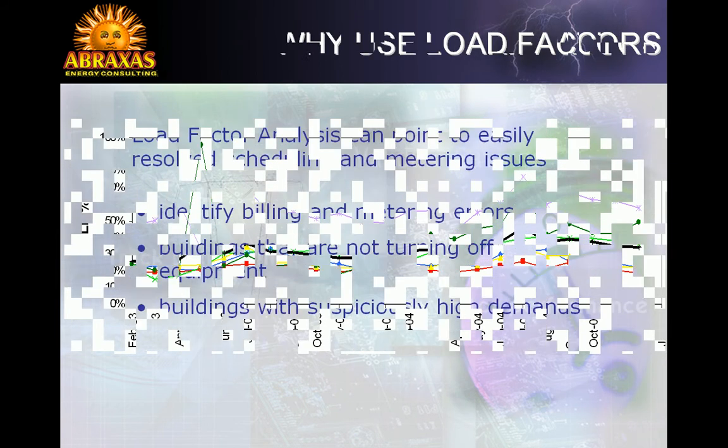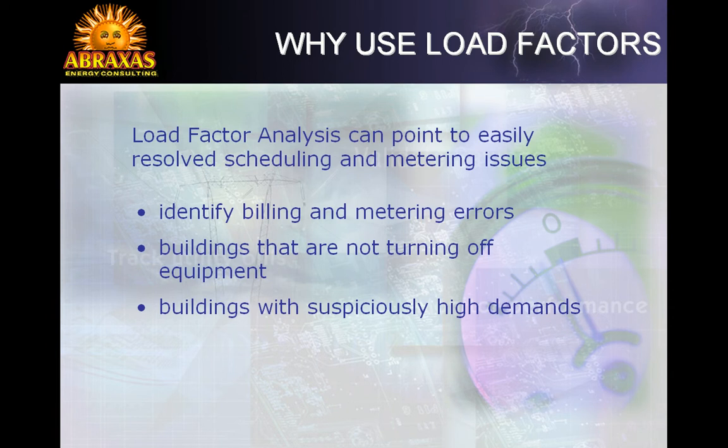Load factor analysis is an art, not a science. Different building types, for example schools, offices, and hospitals, will have different typical load factor ranges. Since hospitals run many areas 24 hours a day, one might expect higher load factors than for schools, which can turn off virtually everything at night.